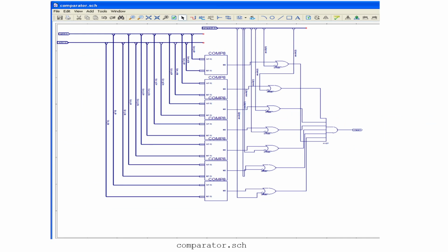Here we have a comparator. I would like to point out that this is not just a normal comparator. We can see we have introduced the concept of mask matching here. For every comparator, we have a mask value. So 7 comparators, with the 7-bit A mask going to each and every output of the comparator, and this leads to selective byte comparisons to yield a final match signal.